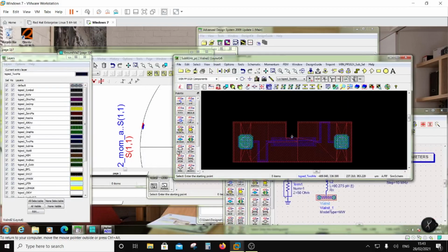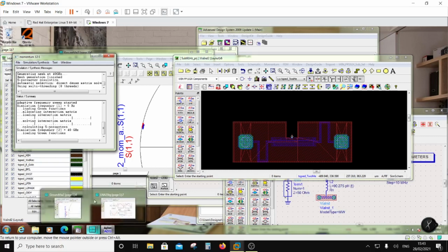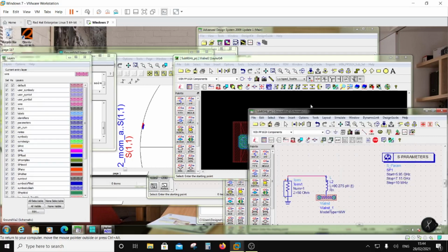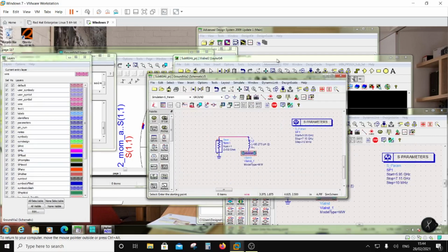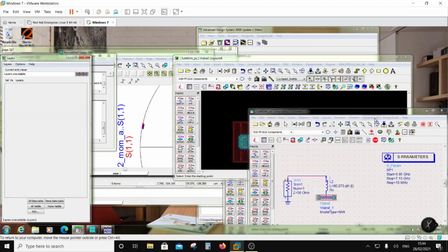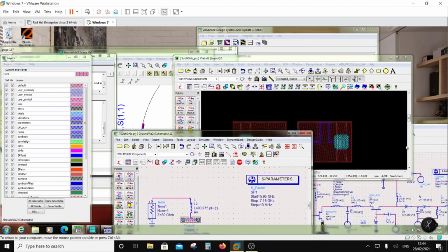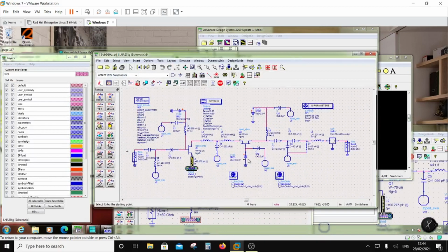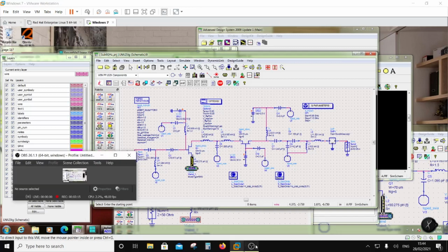So 0 to 40 gigahertz, and then I can make a lookalike. Like over here, I can make a lookalike, and then I can introduce that lookalike in my circuit and resimulate the circuit. Now if that requires retuning these components, that I will do. So in this part I am just going to replace this source inductance with the lookalike from the layout. Okay, thanks, see you in the next part.